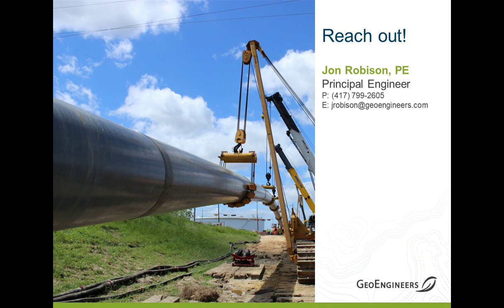But as far as minimum, we typically will start out at 100D, similar to what you would see on an HDD. And then, as you might have to do on an HDD design, you might whittle it down a little bit from there. But a lot of it depends, when you start getting lower and lower, on how your pipe stresses play out.